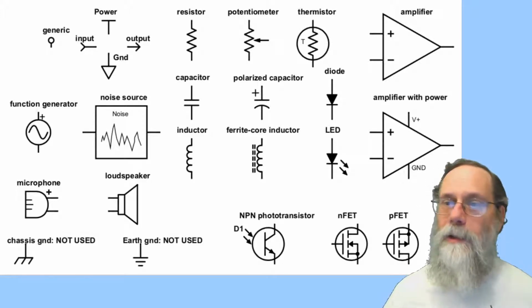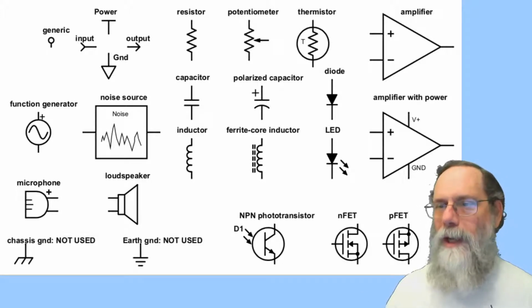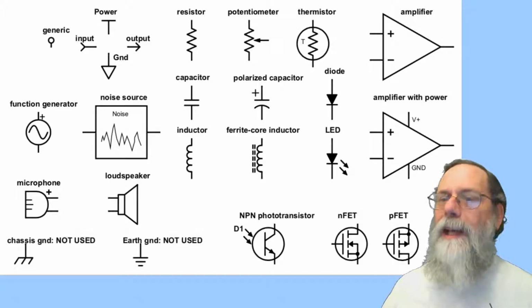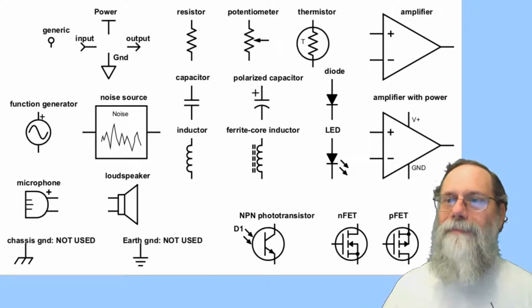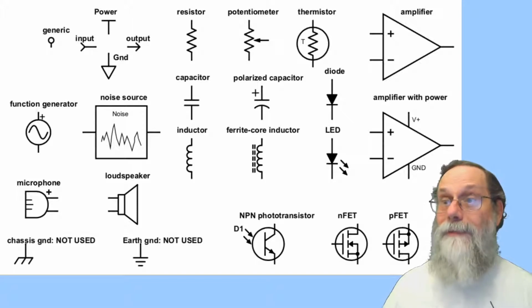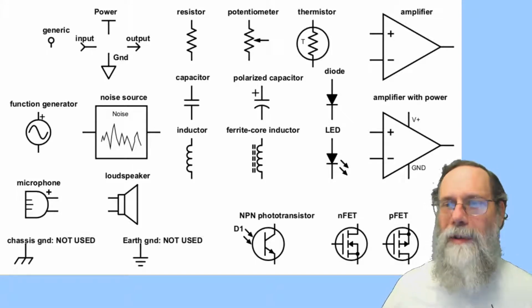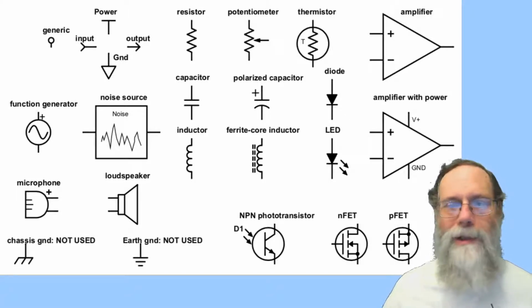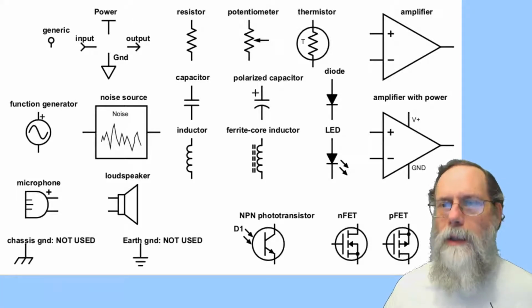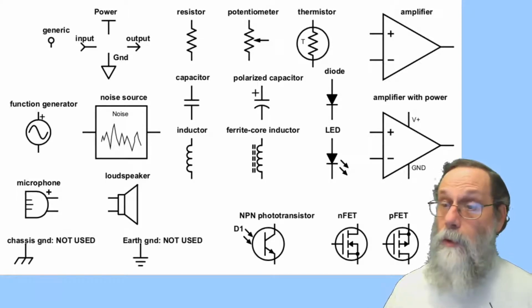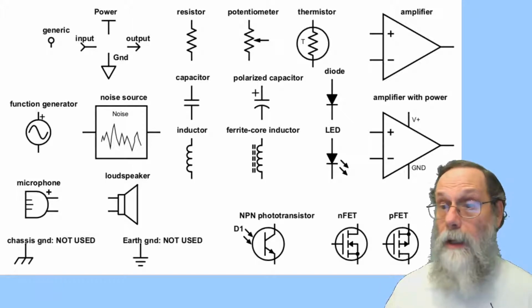Important for radio electronics because radio propagation depends on there's a ground plane down there that interferes or is used in various ways in radio propagation. We're not dealing with that. The grounds we use are just arbitrary nodes in our system. They're isolated grounds, and we don't want them to be confused with earth ground because they're not the same thing.